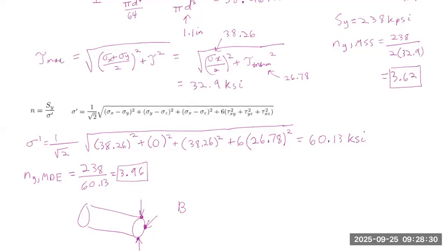There is no normal force due to bending moment on this face since this face is located at the neutral axis. So as the beam bends, the stress element over here will not be in tension or compression because it's located at the neutral axis. However, there is still going to be shear stress from torsion at this negative z location because as we twist the shaft, we have shear stress vectors going this way, and at this location, there is an associated shear stress vector as well.